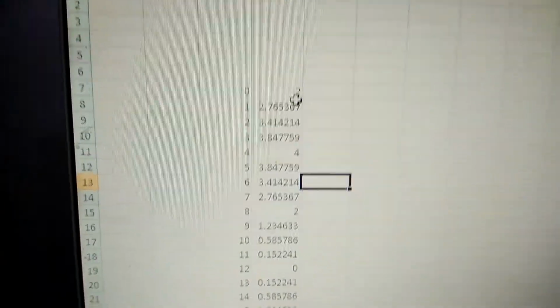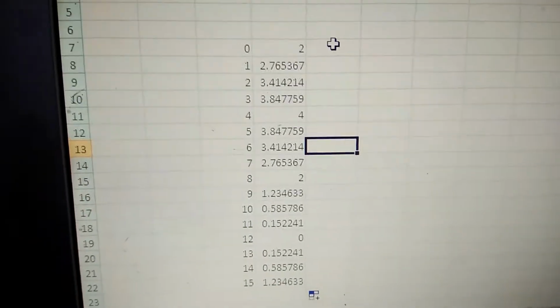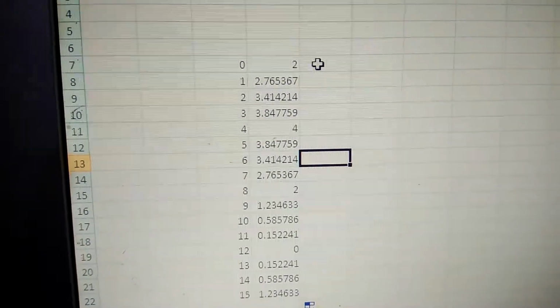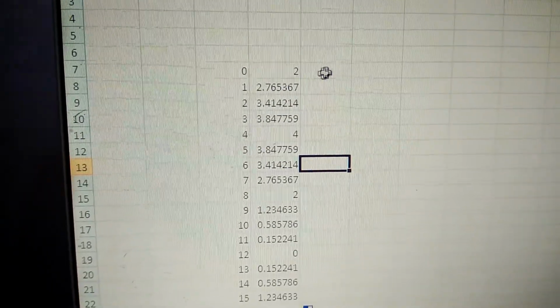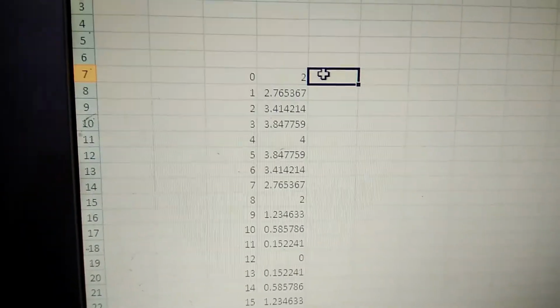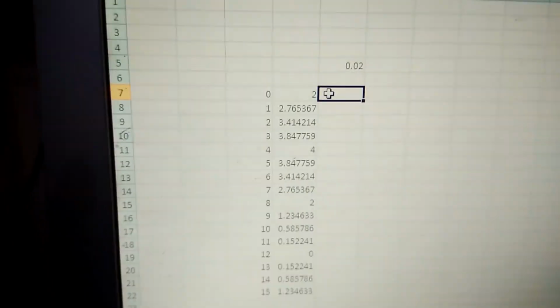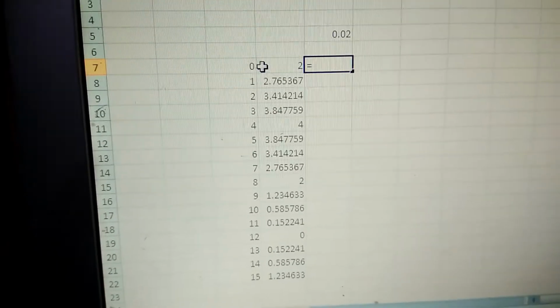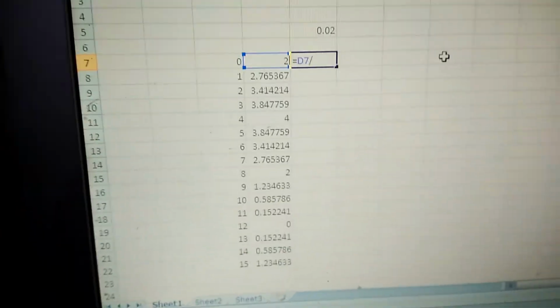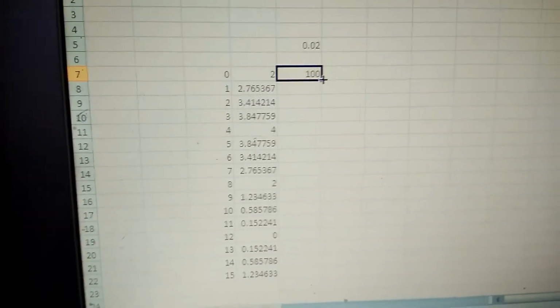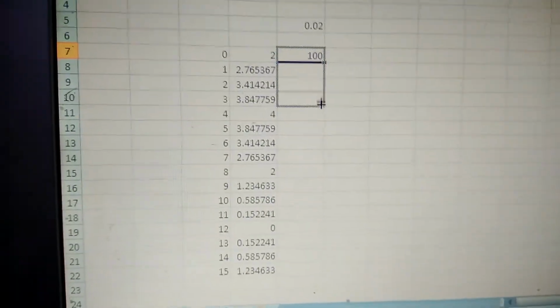Most DACs require the digital value in integer form, and they will not support decimal format. So what you have here are voltages, and you have to convert them into the appropriate hexadecimal value. You simply divide the voltage by the step size, and the step size of the DAC I have used is 0.02. So the value for getting 2 volts is 2 divided by 0.02, which is 100. When you give decimal 100 as input to the DAC, it gives an output of 2 volts.